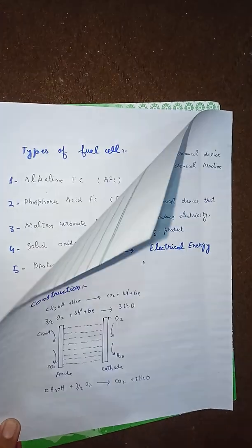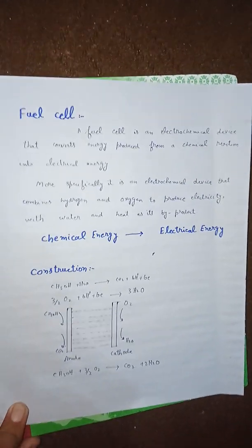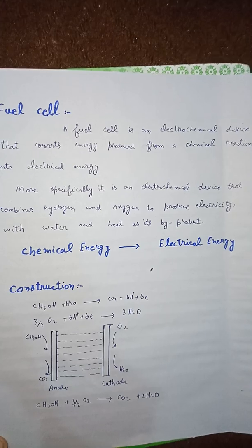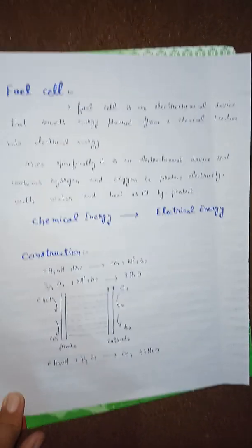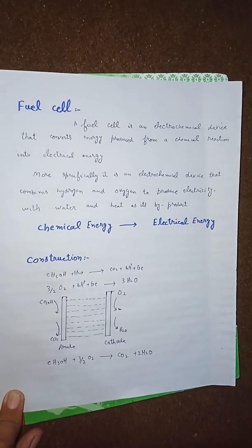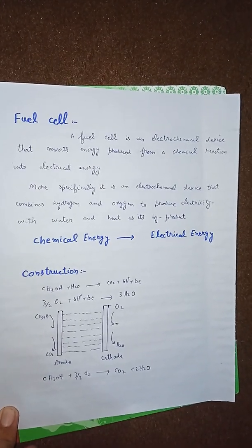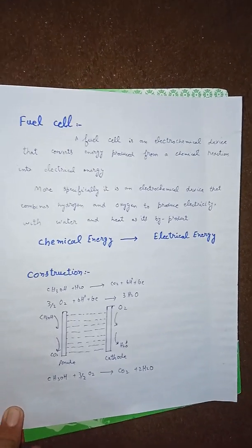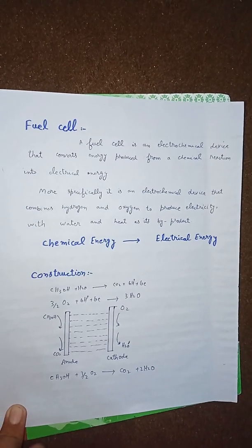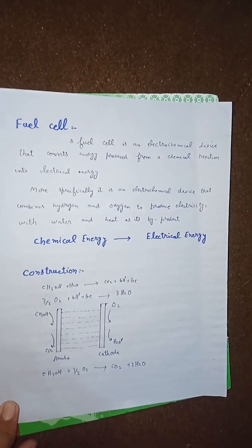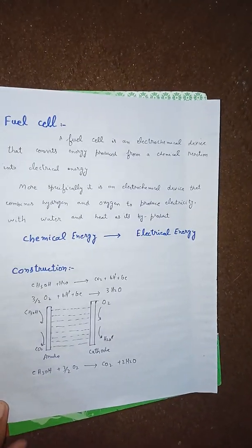When hydrogen gas is introduced into the system, the catalyst surface of the membrane splits hydrogen gas molecules into protons and electrons. The protons pass through the membrane to react with oxygen in the air, forming water. The electrons, which cannot pass through the membrane, must travel around it, thus creating the source of DC electricity.